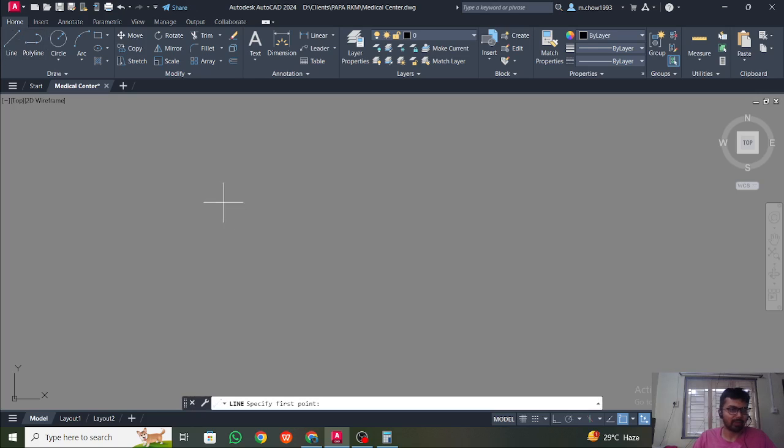Okay, now when you start the modeling here, when you take the line, or you can also click on L, enter, you will see we can draw the line anywhere, and this is the ortho. If you click on ortho, then you can draw only at 90-degree angles here. Okay, so here you can practice along with me, obviously. This is the purpose of this whole tutorial.